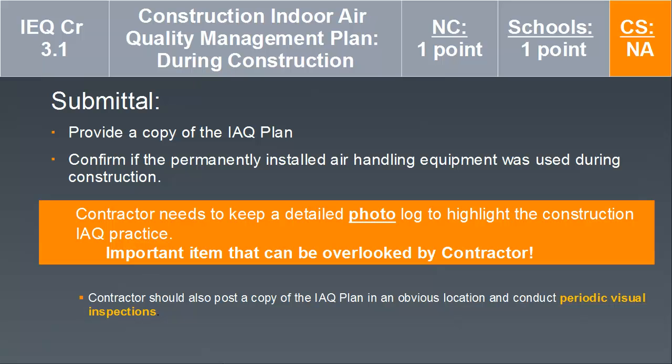For the submittal, you need to provide a copy of the Indoor Air Quality Plan and confirm if the permanently installed air handling equipment was used during construction. If so, then you need to replace those filters.